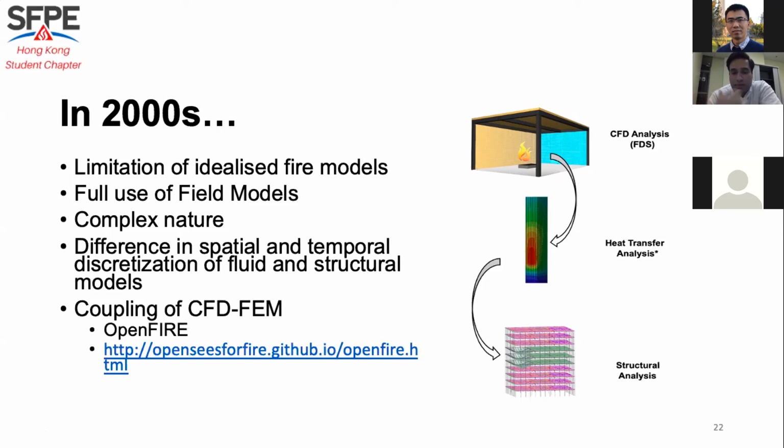One thing I also want to mention here: whenever you are performing CFD, the user must be very careful when using different boundaries and explaining the physical model, because a change in any condition would give you a drastic result, because CFD is quite sensitive to each parameter. So be careful when you're using CFD.